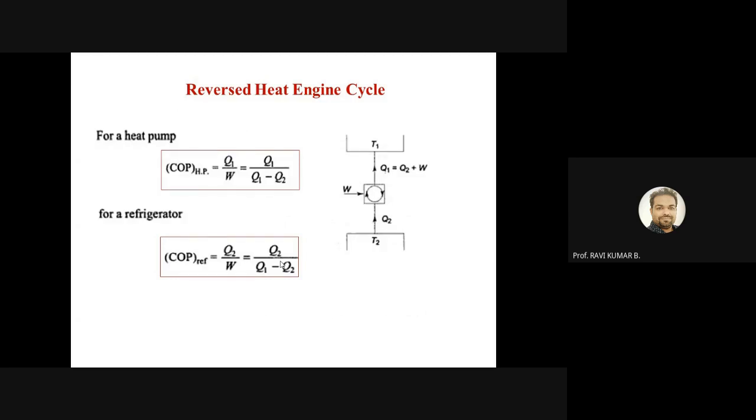So if you keep changing the refrigerant, the amount of heat transfer will also change. In the reversible or theoretical case, it will not be bothered about the type of refrigerant to be used. It will only be concerned with the lowest possible temperature and highest possible temperature of the cycle. So it will be a function of temperatures only.